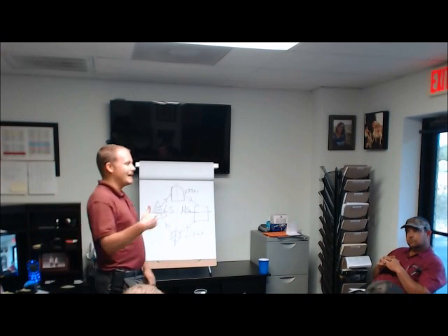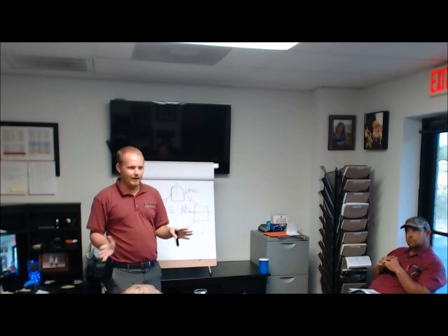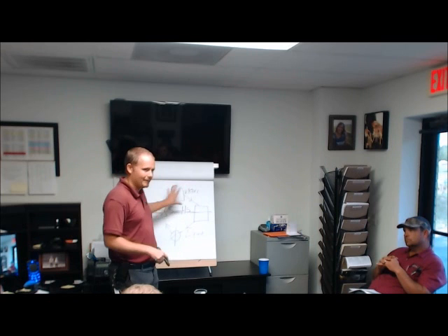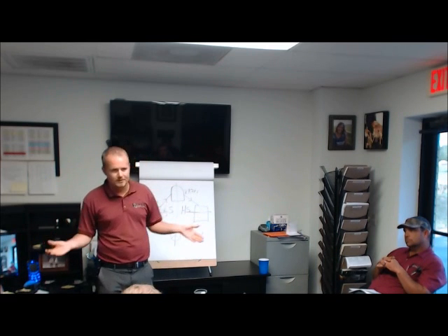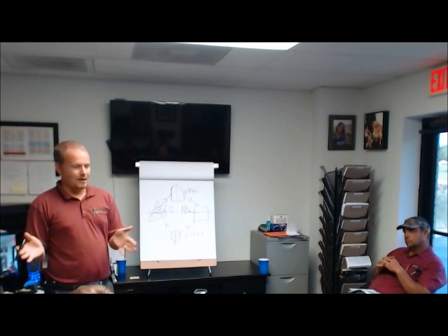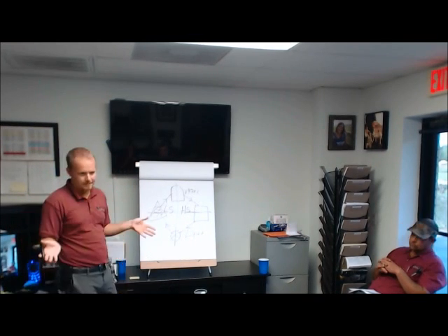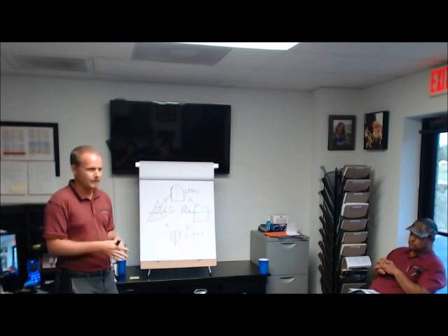But that's only because I understand the 5 pillars. If I didn't understand what was supposed to be happening here, I could easily get confused about it. Because what is a cold suction line or a warm suction line telling me? It's really just an inaccurate measurement of superheat. Okay, by actually using a thermometer, I can tell you exactly what the number is, right?